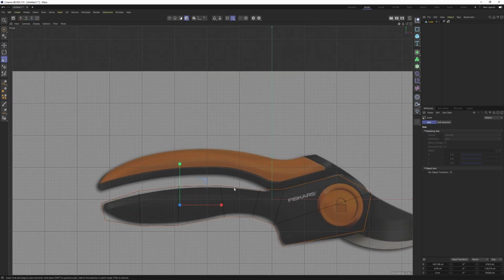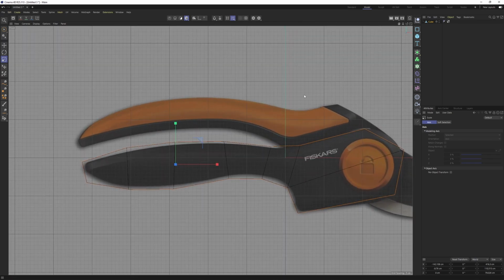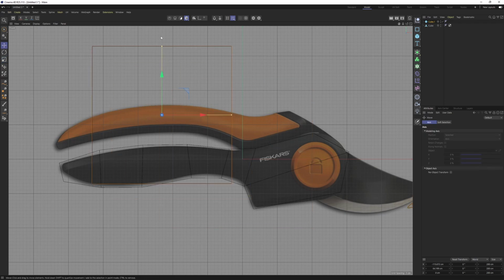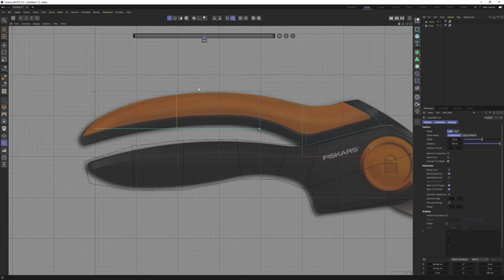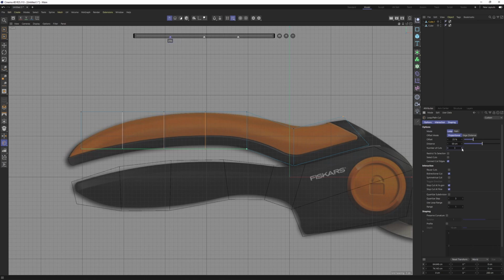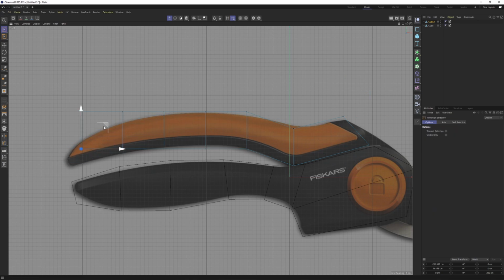This one looks okay. Now another cube. First scale, make it editable, polygon mode, press Control, extrude. One more time, points mode. I will press Shift at the center loop cut. I will add, let's say, 3 again, 3 cuts. Switch to points mode.